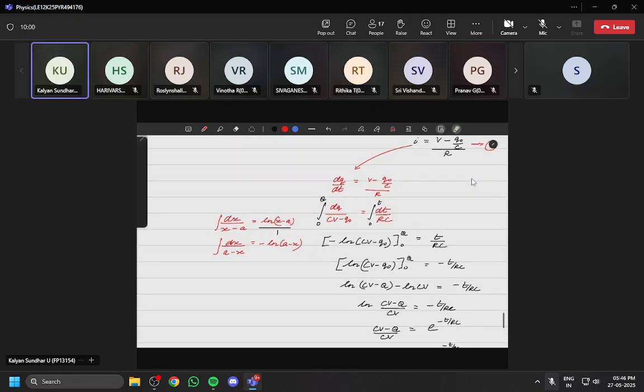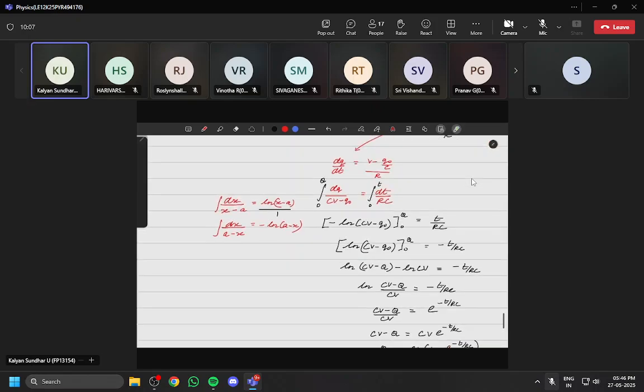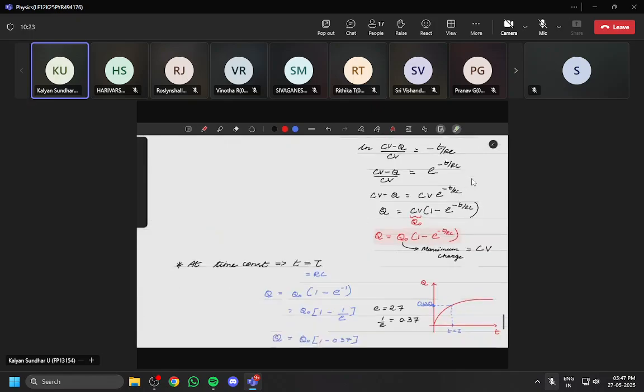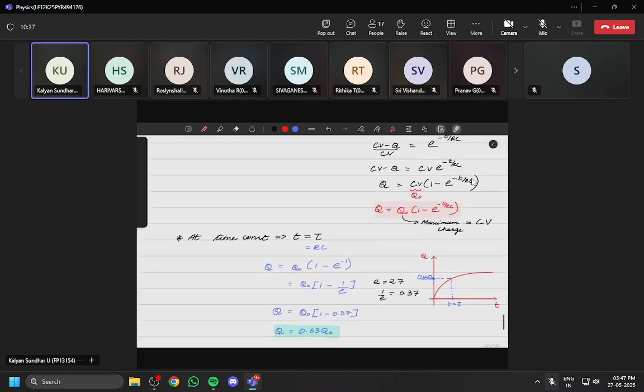And this is the one which I'll be differentiating with I is equal to dq by dt. I will be differentiating with the values. Initial charge has been 0, going to the maximum value Q it reaches. Similarly, time goes from initial time 0 to time t. What will be the potential, what will be the charge, what will be the current? So this is your first value, the charge. The total charge accumulated: Q will be equal to Q naught into 1 minus e to the power minus t by RC.